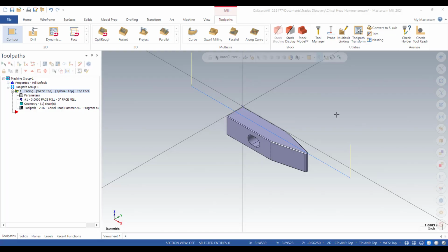Okay, next we're going to machine the shape around using the contour toolpath. Before we get there, let's put the facing toolpath, what we just created, to sleep. How you do that is that you make sure it's checked, and then we just press this display button. So that way now it's not showing on the screen, but the toolpath is still there.